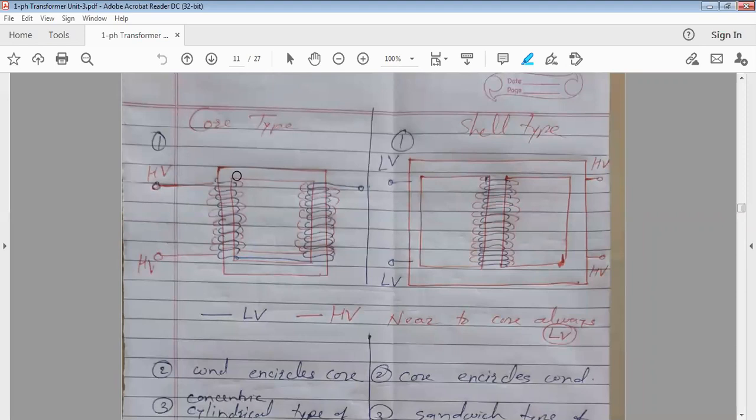All of you can see initially the blue winding is there, that is LV. So what is done? See, suppose it's a core type. तो क्या करते हैं पहले? LV turns. I have started from here. Suppose from A end I have started LV. Then up to this the turns I'll wound. Then the same it continues on the other side limb also.